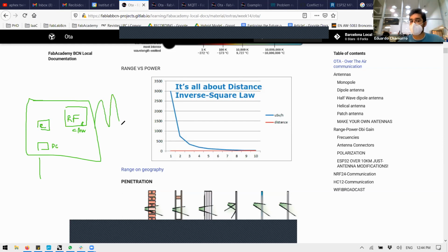Because we're working with frequencies, how well you modulate your frequency is everything. If there is just a microsecond difference, you mess up everything. So the timing has a master importance. These modules are easy to spot because they have a metal shield. For example, you can see on your ESPs, they have a metal casing. They are covered with metal, compared to the ATtinys. Why? It's a Faraday insulation box.